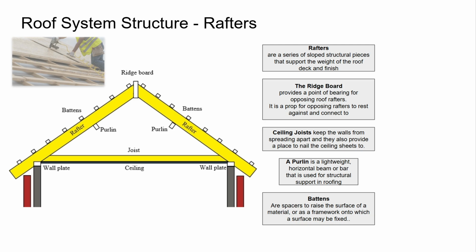It all depends on the structural engineer. Okay, but there's a few other things. There's something called a purlin. The purlin is a board that sort of keeps these things from wobbling sideways, in and out of the page. So it's just something that gets hammered into each rafter, and it keeps the thing steady sideways, front to back.